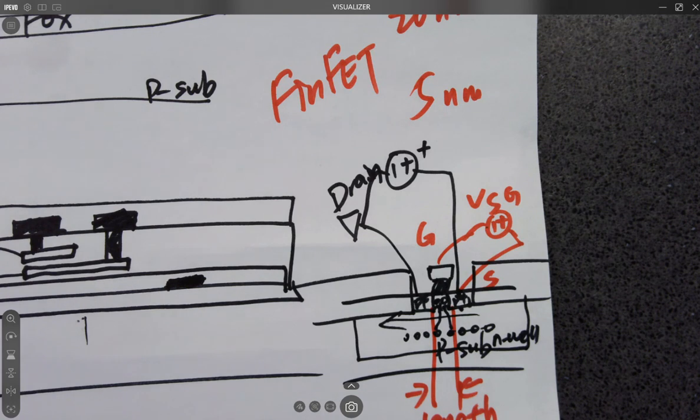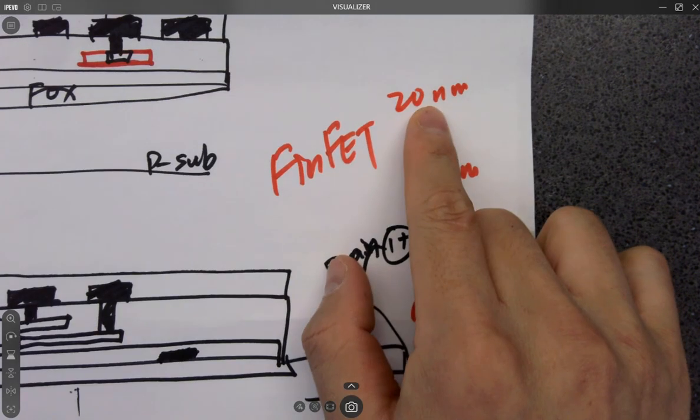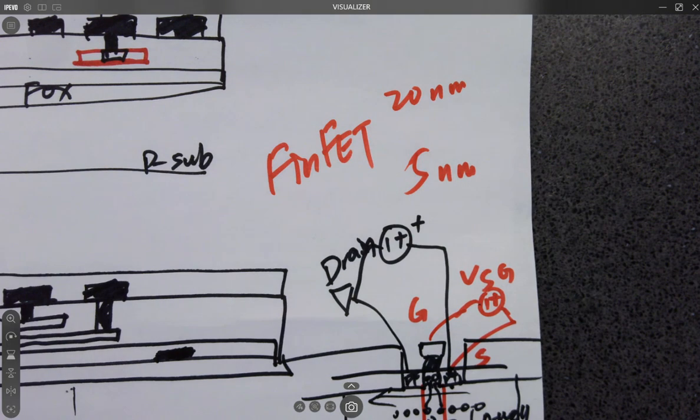So what's going to happen is there's a new technology called FinFET. It's not really new anymore. I mean, it's like 8 years old already. Anything below 20 nanometers, okay? It provides the technology called FinFET. It's like a fin, right? And then the gate is not just one dimension anymore. It's 3D. It's wrapping around that channel. So it's providing enough electric field around the channel in order to attract enough holes in the channel. So it's wrapping around it, called FinFET.